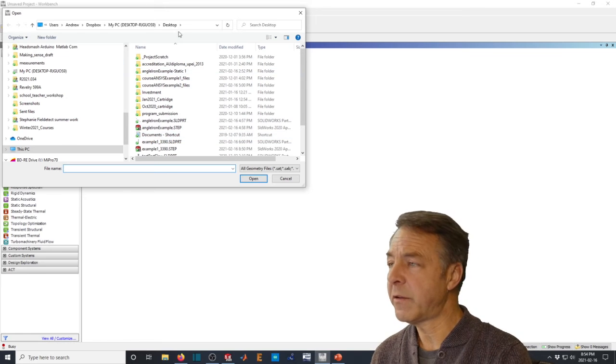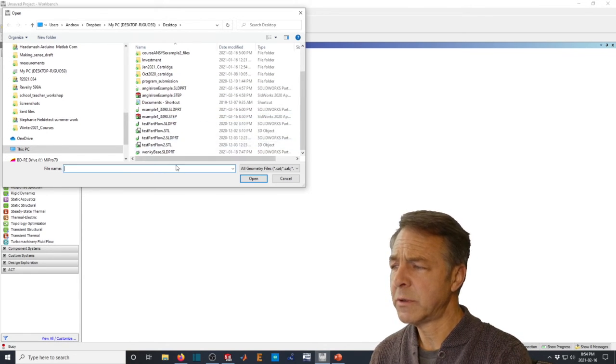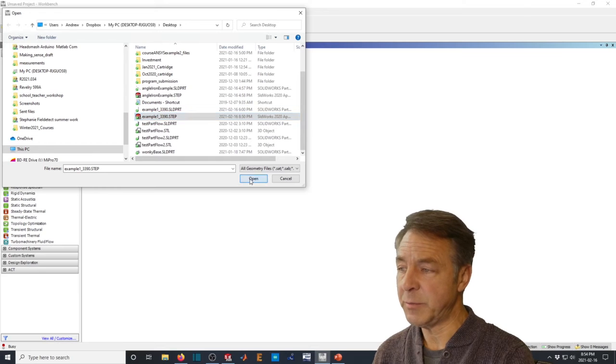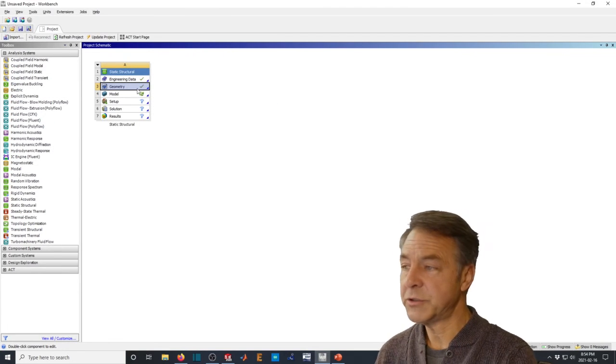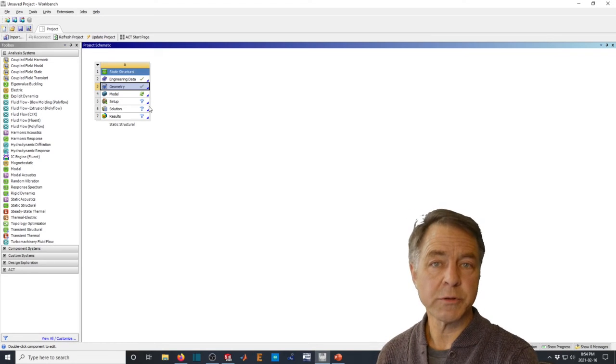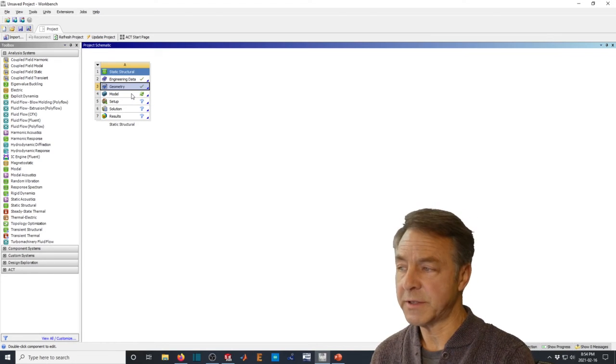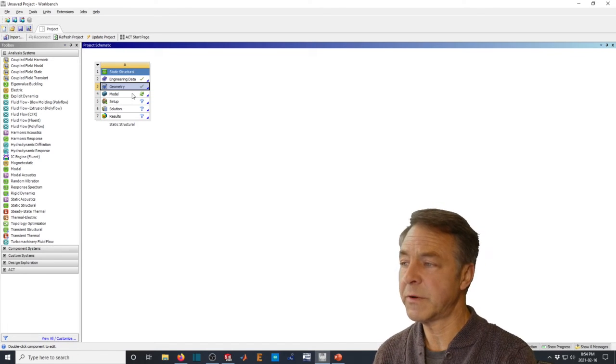The step file that we created in the previous example, we should be able to find it here as a SolidWorks STEP file. And if we just simply import that, it imports directly as a solid into ANSYS from the stored file.